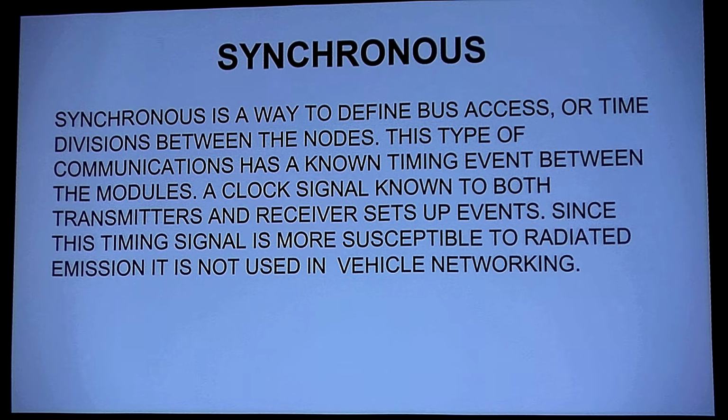We have synchronous. Now, synchronous is an idea of timing. That means that every module on the bus has a common clock. So I have one master controller that sends a clock signal out to all the other modules. Does that make sense now? So each module isn't keeping track of time. I've got a master, and the clock is being shared between all of the units. This has a lot of edges. And if I have edges, lots of changes, you know how we saw earlier, how you see these little bits and they come up and they go down? The faster that these buses are, the more radio emissions they produce.